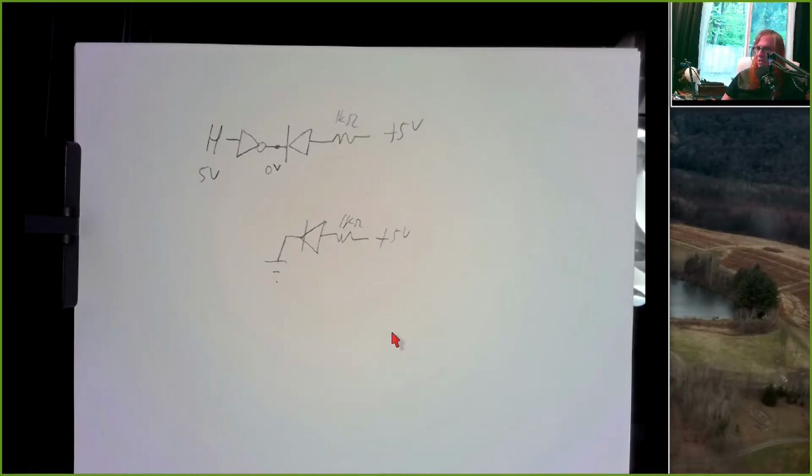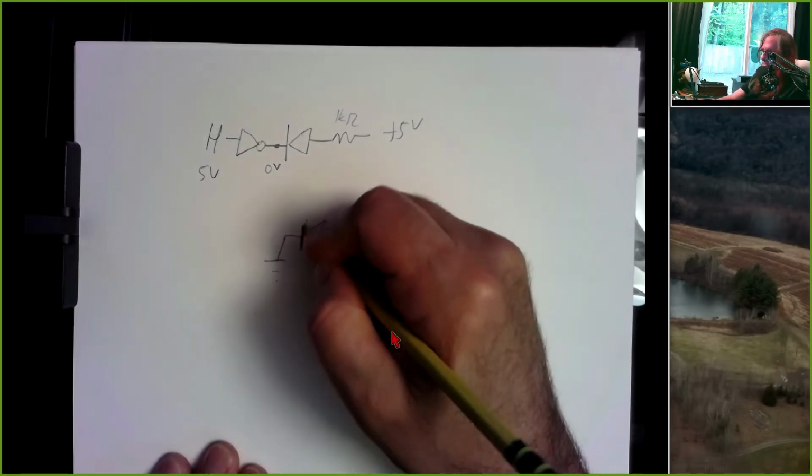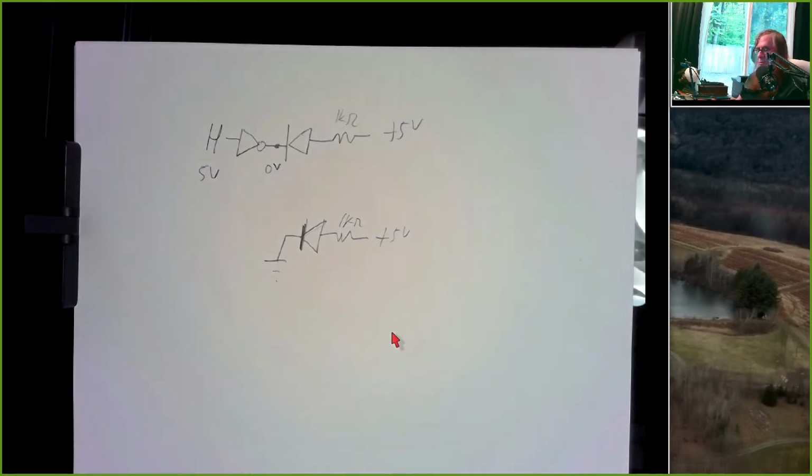So if you had a configuration where it didn't light, I suggest go back and take a look at your circuit again and see if you can figure out what's going on. In this third configuration in particular, one thing that sometimes happens is people get the LED hooked up backwards. And it's pretty easy to do. The directionality is almost the same unless you look for the little bend in one of the pins, or you hover over those pins in Tinkercad and wait for the pop-up to say, you know, anode or cathode. So go back and redo your circuits sometime and make sure you can get all three configurations to light up.